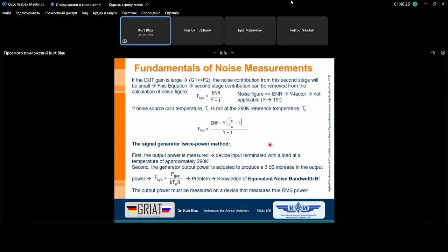And the power amplifiers, for instance, on satellite platforms, in a lot of cases have electronic tubes, traveling wave tubes, and such power amplifiers based on traveling wave tubes have noise figures in the order of 25 or 30 dB.